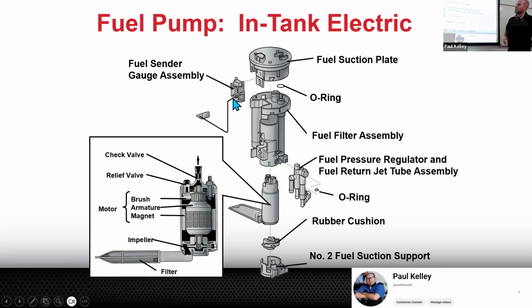If you go back to the throttle position sensor, this thing works the same. It gives a 5-volt reference into ground, and the signal wire is going to change between about 0.5 volt and 4.5, depending on if it's full. Maybe 0.5 volt is almost empty, and 4.5 is almost full, right? So you could just sweep it. It's an easy test, except it's in the fuel tank. So it's kind of like, yeah, dude, I could fix it, but it's not really gonna be cheap.